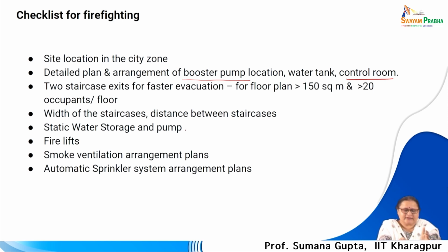Static water storage and the pump location are to be known to the firefighting people. Fire lifts, if any: I have discussed fire lifts, which are a dedicated lift, a staircase and a lobby, which together are called the fire lift, and should be in place if it is allowed or sanctioned.